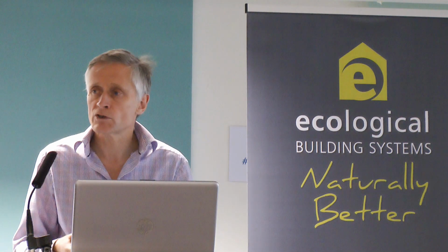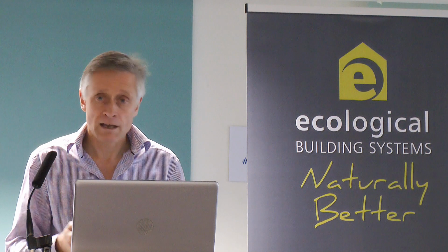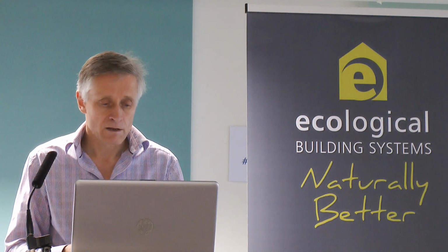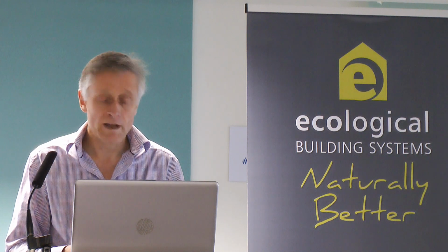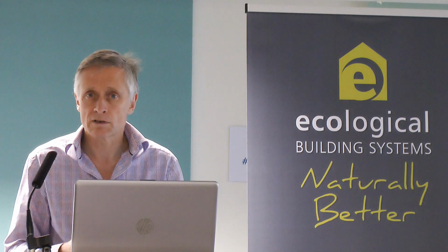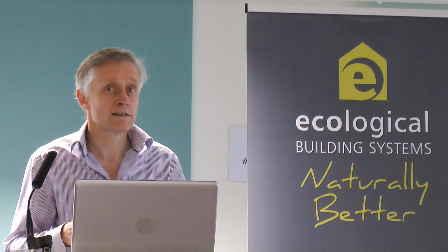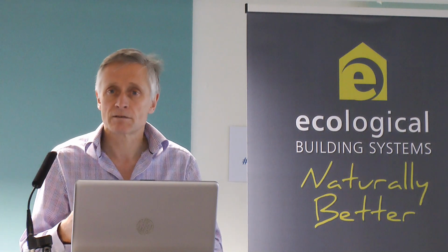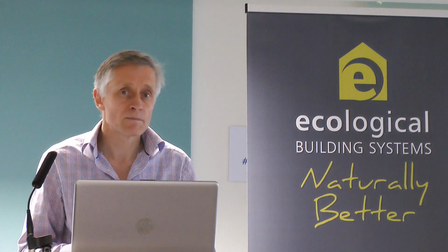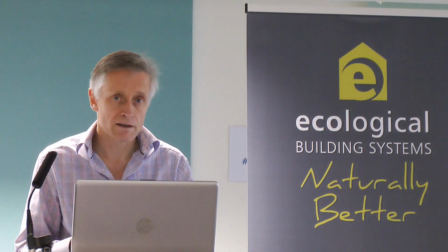As I said, it's almost impossible to measure in situ with any real degree of confidence. It can be done, but it's very laborious and complicated. So we have to rely on the existing tools at the moment, which are the U-value calculations and condensation risk calculations. But bear in mind at the same time that all these other things are going on, particularly gaps and cracks, heat escaping through these gaps and carrying moisture with it. And that's the big takeaway, I think, to remember this and try and guard against it.